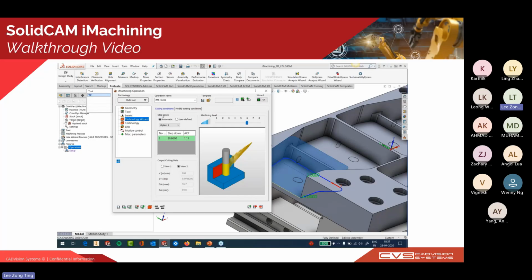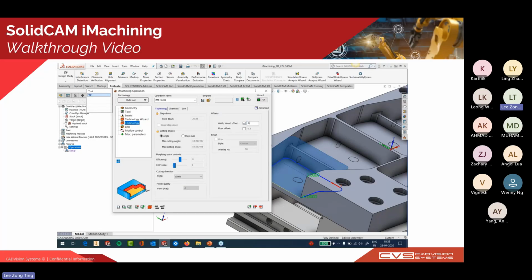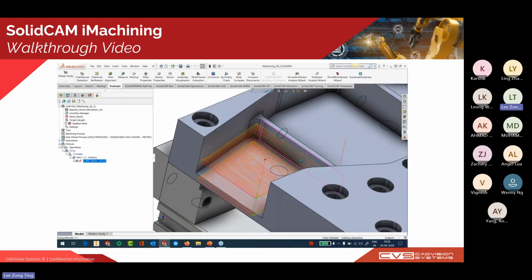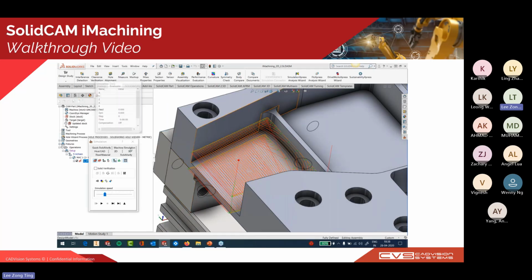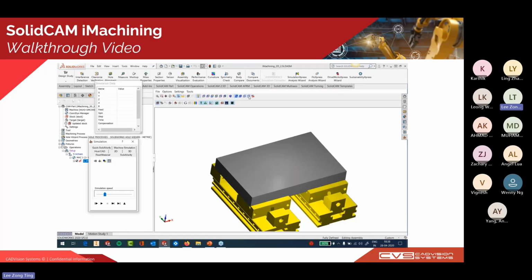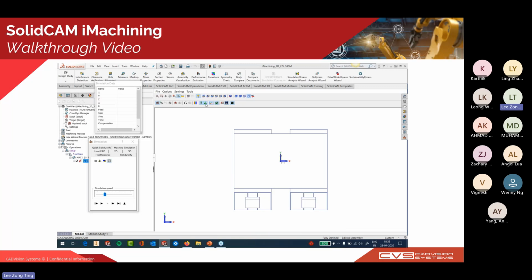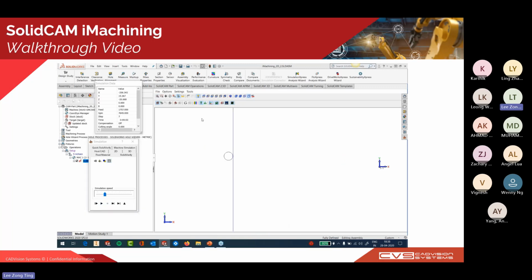You can also see the ACP right now is in the green zone, which means there are fewer vibrations on your tools. After we calculate the toolpath, you can see the toolpath gradually conforms to the geometry of the fillet on the corners. We'll go ahead and simulate it, and pay attention to the simulation data on the left here.